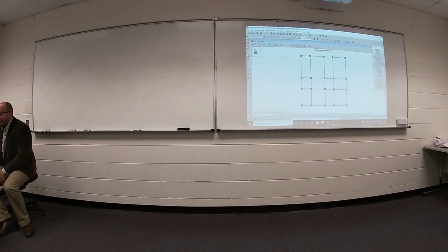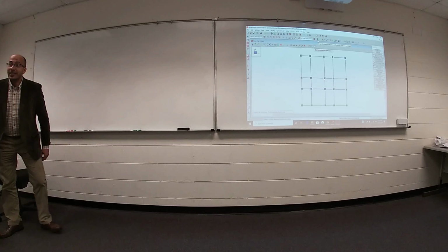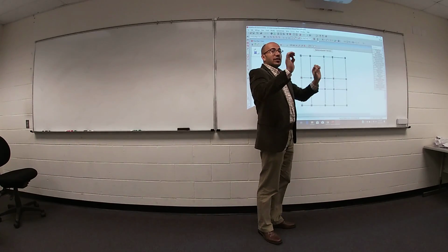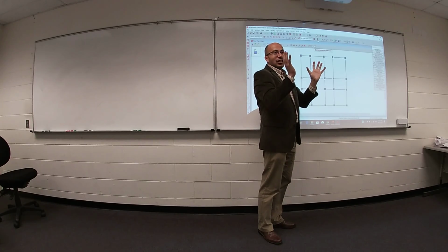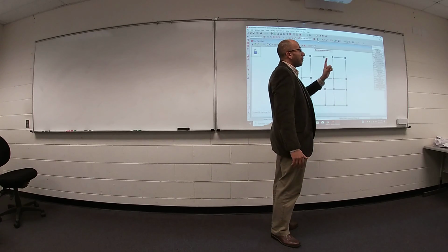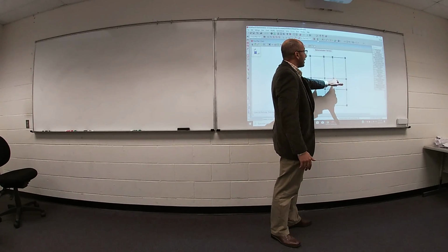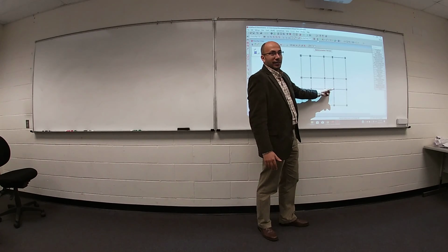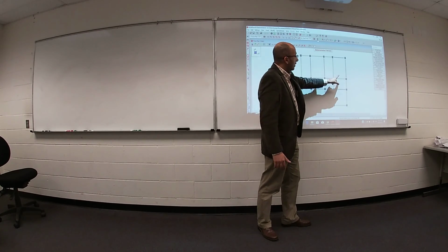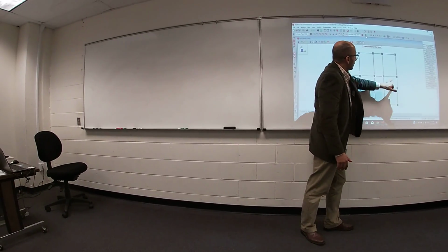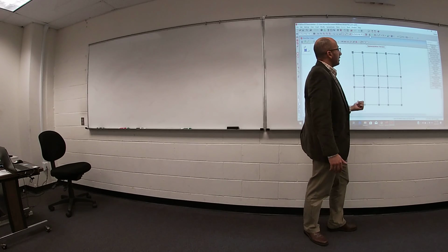If you would like to see the slab, check extrude view, this icon. This is the reason why I said after each step, make a check. You did everything correctly. So, yeah, I cannot see my slab, but your slab has a green edge. Your beam has blue lines. You can see it? This green edge is your slab. These blue lines are your beam.